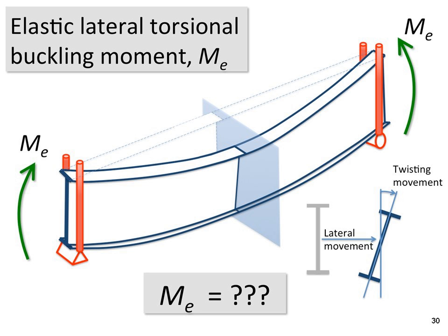For a circular shape, it does. For any non-circular shape, it does not. The polar moment of inertia, by definition, is the Ix plus the Iy, and you should find for a circular shape that that sum is the same. But for all other shapes, you'll find that the sum of Ix and Iy does not equal J, the torsion constant.